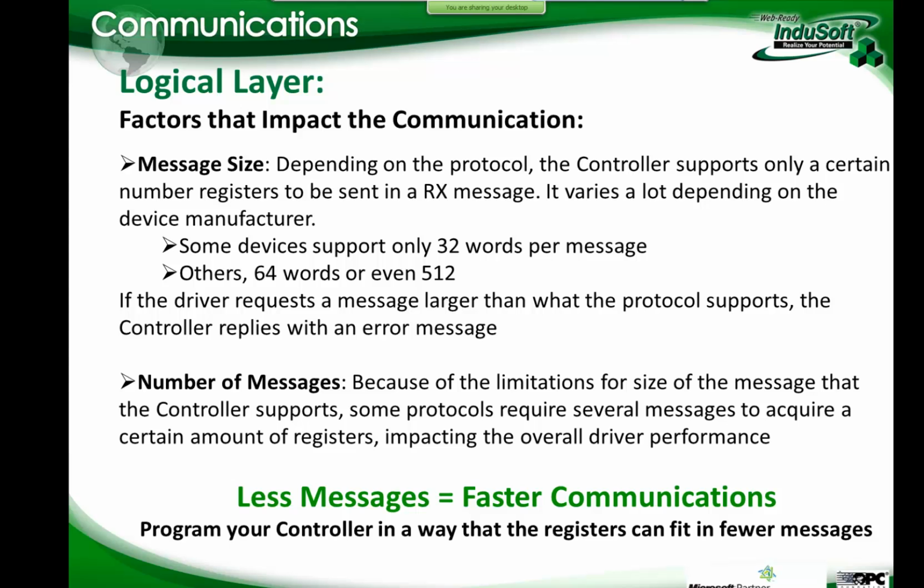Okay, so let's say that you have a Siemens PLC and you have the DB1, DB2, DB3, DB4. The protocol says that for each one of these DBs, you need to send a different message. So if you want to optimize your communication, you may put all the HMI communication in just one specific DB. So we can send just one message, and we can read 1,000 bytes on each DB per message. Okay, so knowing your protocol is going to be one of the ways that you have to optimize the communication between your HMI, your SCADA, and your PLC.